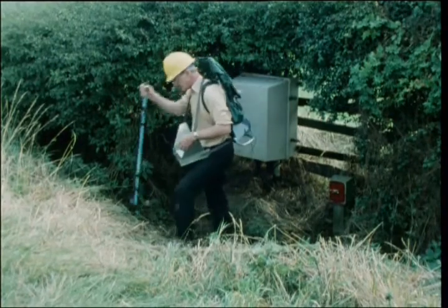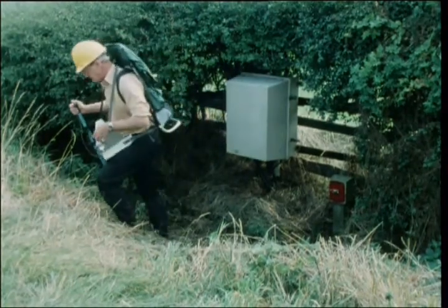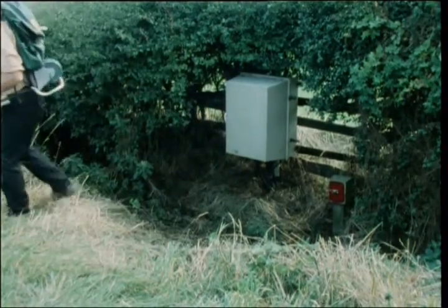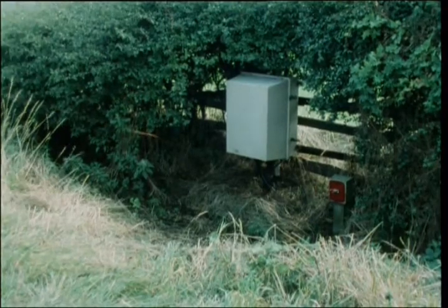To make certain that the pipe is protected along its entire length, it is possible to walk over the pipeline and at intervals measure the potential against the reference electrode on a pole.